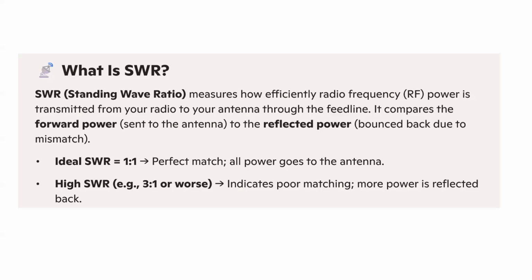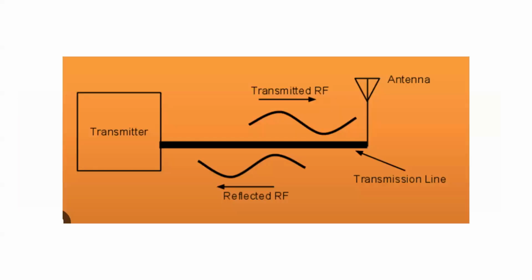But I am going to flip back to this diagram and say, for multi-band antennas, sometimes we tolerate a medium or high SWR, something more than 2-to-1.